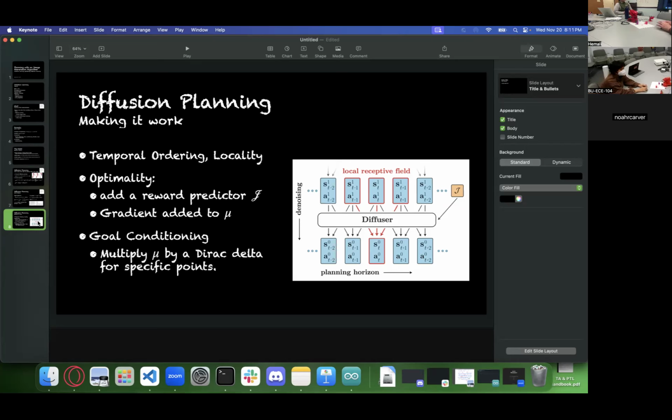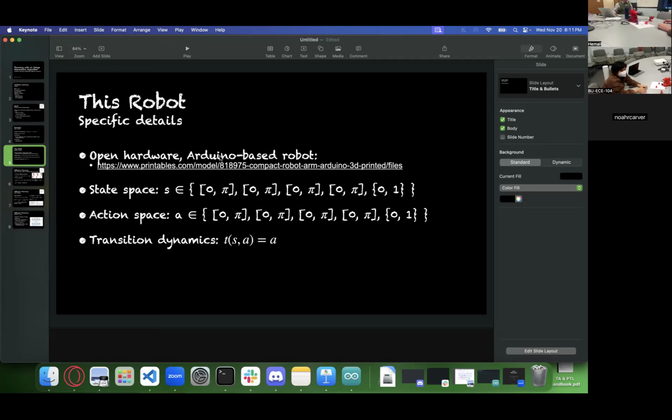I don't know if this is stupid, but... No, there's no stupid question. So what was the data for this? So the data for this, we have a state space, which is 4 angles and a Boolean. Okay. And then, about 216 times per second, it will query from our controller what angles it's in, and it'll try and put the robot in those angles.